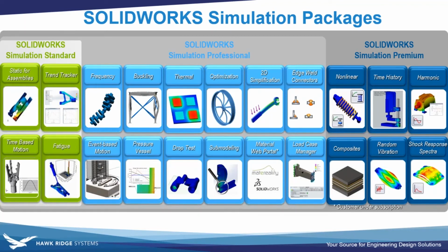But if we're also talking about durability, or making sure that something is going to pass the test or withstand a certain load, then you can also run a fatigue analysis, where we can input some sort of SN curve in our material definition and take a look at whether your part or assembly is going to fail after a certain number of cycles. Right? So we're trying to test not only in the moment, but to see whether things are going to pass down the road.